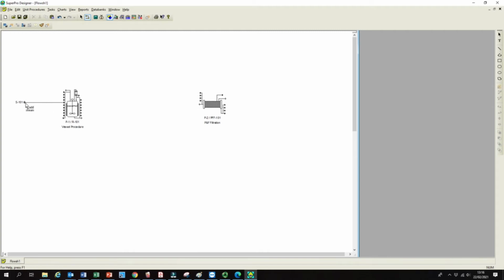Either we can add reactant A, reactant B, or your solvent, anything through this stream. And then let's do one more. Click somewhere here and then connect it with one of these input ports. And then we can also use the default port to pump our solvent, heptane solvent.